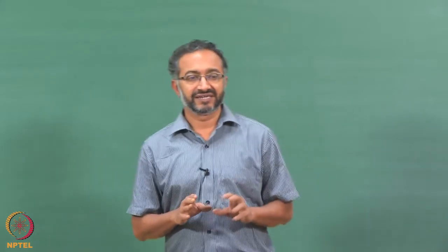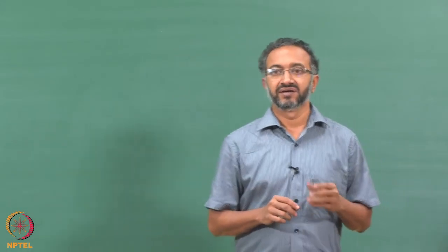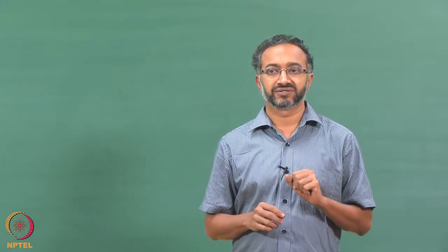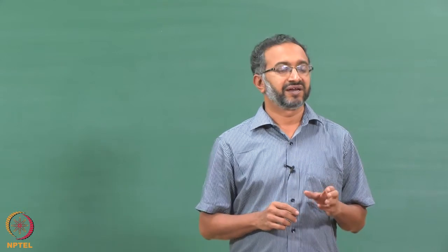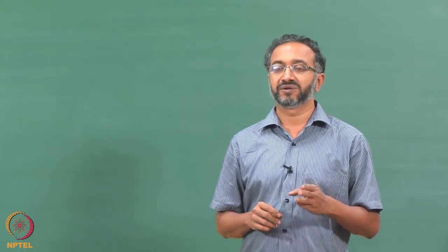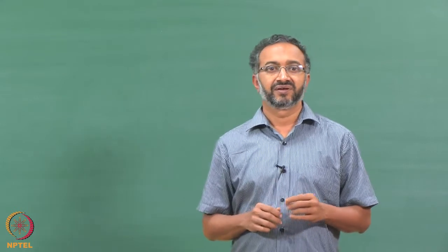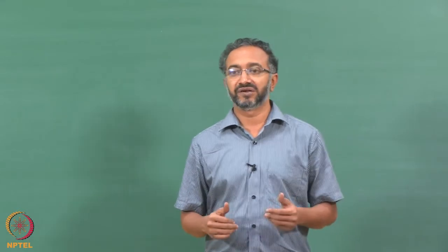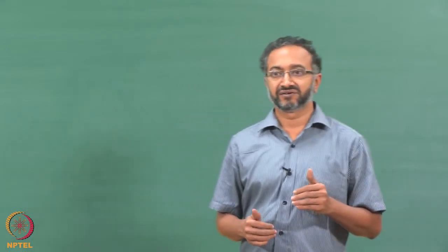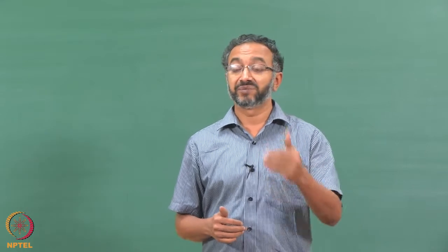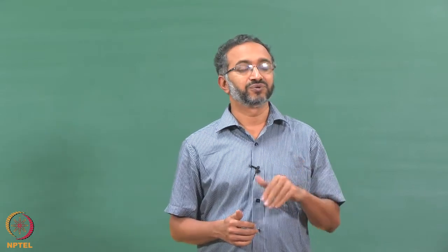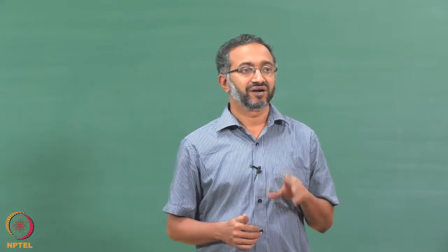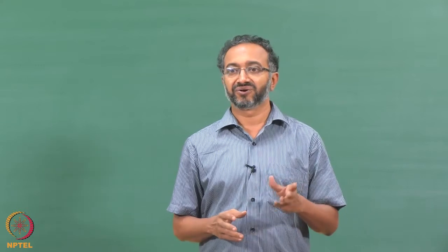So, therefore, we will take an example of cone and plate, look at what kind of assumptions are made to analyze the fluid mechanics of flow within cone and plate, and parallelly we will try to see what are the possibilities where these assumptions break down. And then when we are doing experiments using cone and plate geometry, what are the possible ways in which we can either first know that maybe I will encounter a problem, or two, I will know what are the consequences of that problem being encountered, or third, how do I make sure that the problem is there or not.